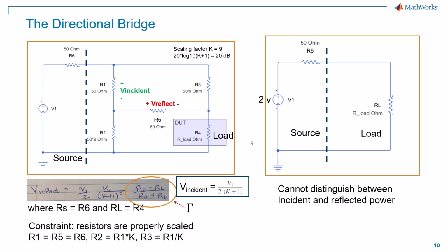So instead of having just RL, we're going to have R4. This is the same thing as our RL in the right side, but around it, we've added 4 additional resistors in this bridge configuration. And the particular bridge configuration I have here is called a 10-to-1 sampling bridge, or a 20 dB bridge. And that is because we're sampling off 10% of the voltage across R1, and we're maintaining 90% of the voltage across the load that it would be in the bridgeless use case.